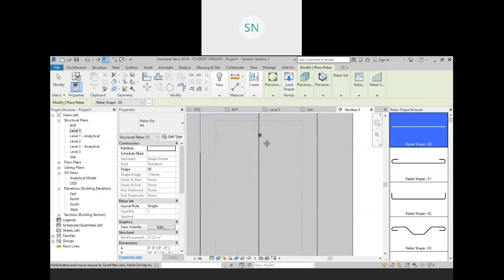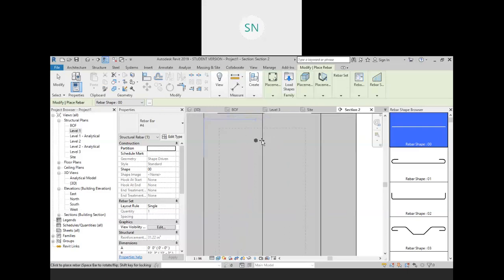Now for example I want to place 3 members on the top, so you have a set also, you can choose a fixed number 3. Now see we have directly 3 options, but as we go close to my placement position it actually flips the side, right? So that's why it is very difficult to place it exactly at the corner. So for that do one thing, make sure your orientation is proper and just place it anywhere, right?